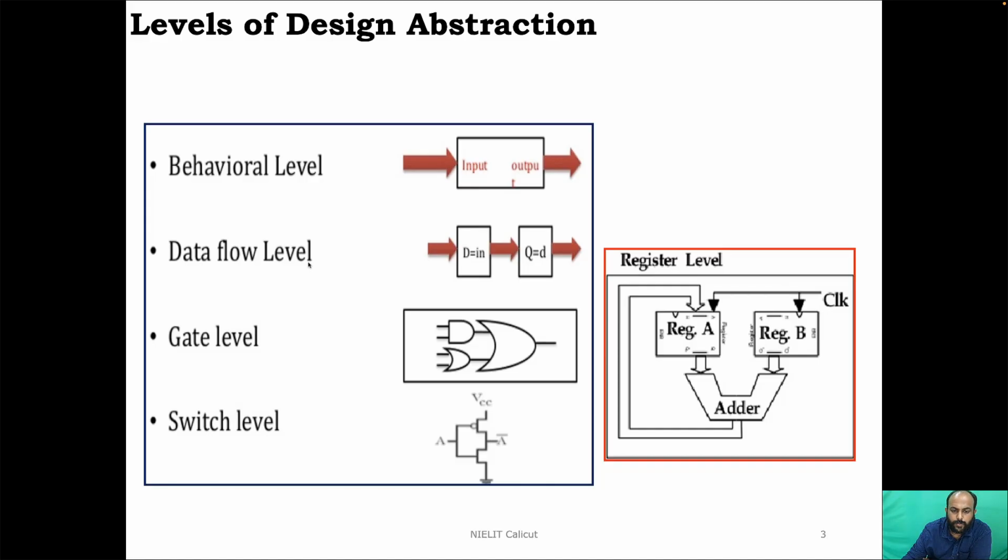And also, we call the code written for synthesis RTL code, wherein RTL stands for register transfer level, wherein the code is described in such a way that how data flows between different registers. So this particular way of writing the Verilog descriptions that can be synthesized is called register transfer level. Okay.